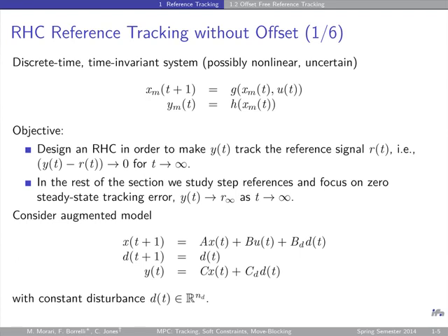If you have integral action and you have a step change in the set point, then eventually, asymptotically, because of the integral action, you will reach the set point without error, and it doesn't depend on your model accuracy or anything. It just depends on the integral action. And so we want to achieve the same behavior here within the MPC context, with the modeling, with the prediction, etc., but with an additional feature that it does asymptotic, error-free tracking for asymptotically constant set points or references.